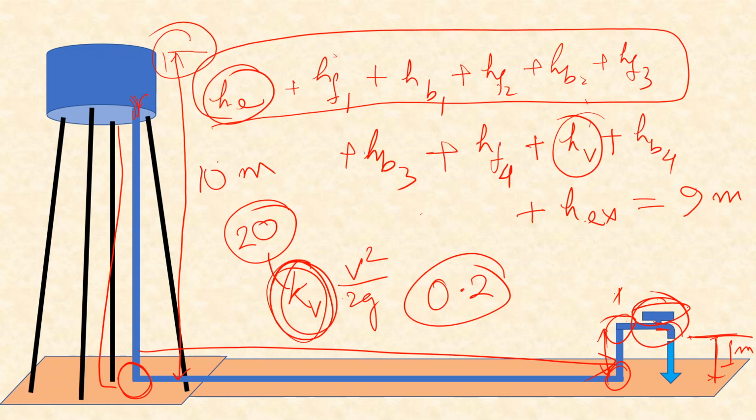Now suppose this was the cross section of the pipe opening at this point, when it is only this much closed, then the value is, suppose, 2 or 3 or 5 or so on. But when this is closed by this much, and only through this cross section of the pipe water is allowed, in that case this coefficient will be of a higher value.